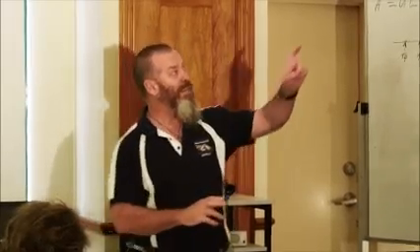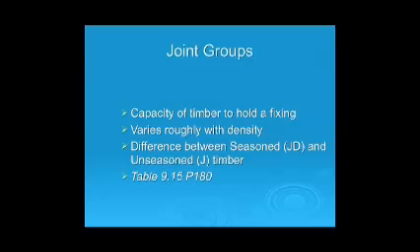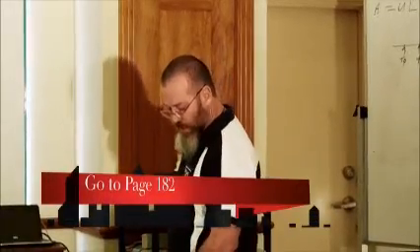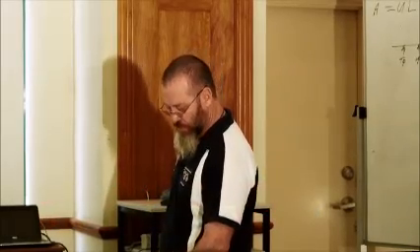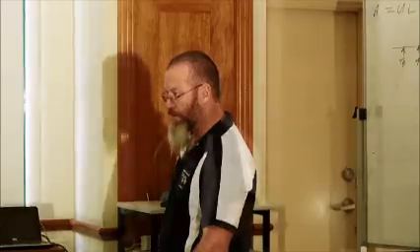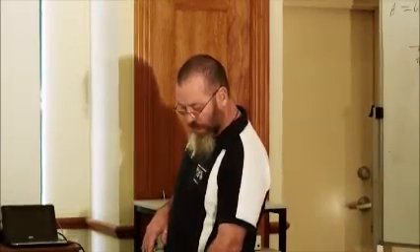There it is there. JD means seasoned timber, which is what most of your timber is. And most of the stuff we're using these days is MGP. So we're all going to work on MGP 10 for our task 57. MGP 10, JD5. And you'll notice there that the difference between North American Oregon and Oregon from elsewhere is a change in the joint group. It goes from J4 to J5. Now when you go up the top, it talks about seasoned softwood. And it talks about heart-in material and other material that's free of heart.